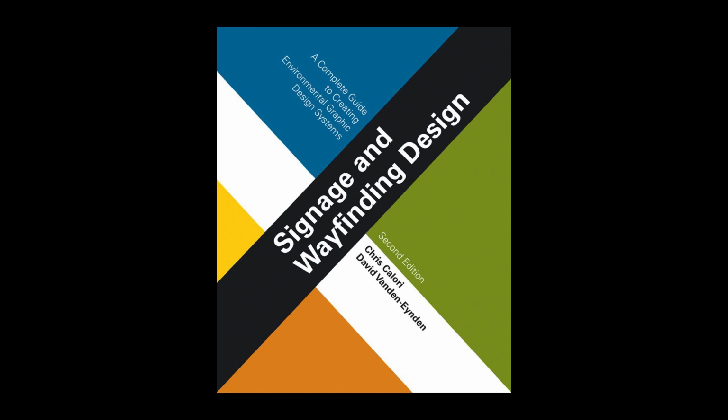In the graphics drawing, the EG designer controls the appearance of the sign graphics for a wide range of message content. The graphics drawings should show each unique layout configuration for each sign type, since a given sign type may display several different kinds of informational content, with each requiring a different layout.